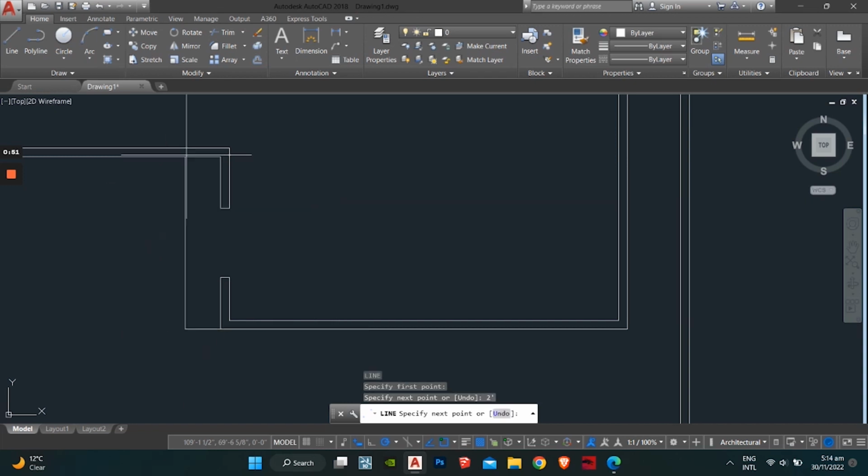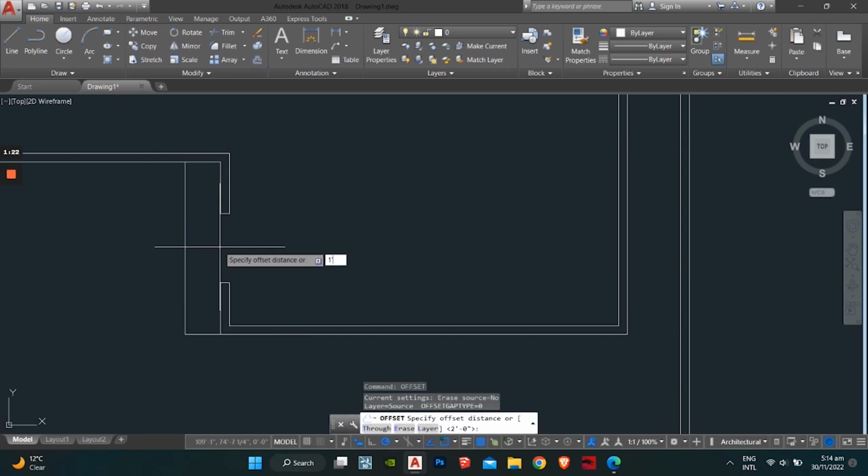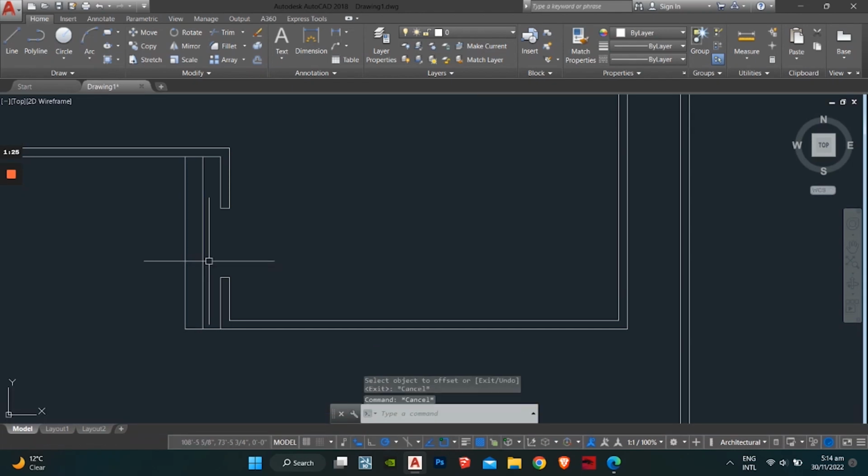And stick it here. And our standard size for stairs is 1 by 6. So the tread has to be 1 foot where you put your foot, and the rise, the riser, has to be 6 inches. So in 2 feet, I need 4 steps. Okay, so I need 1 foot over here. Let's suppose this place is around 1 foot up, right? So I need just 1 step. So what I'm going to do is offset 1 foot, enter. So this area right here notates your stairs.